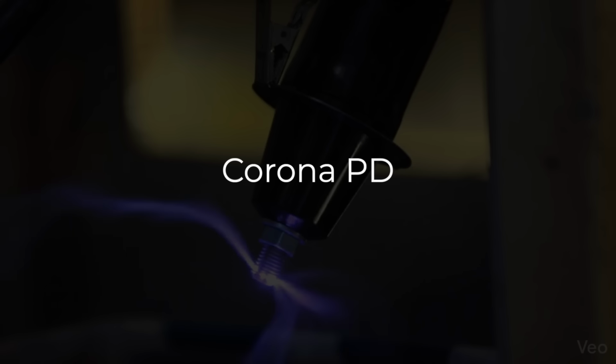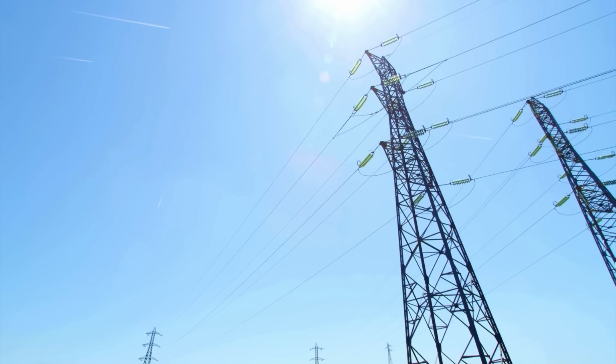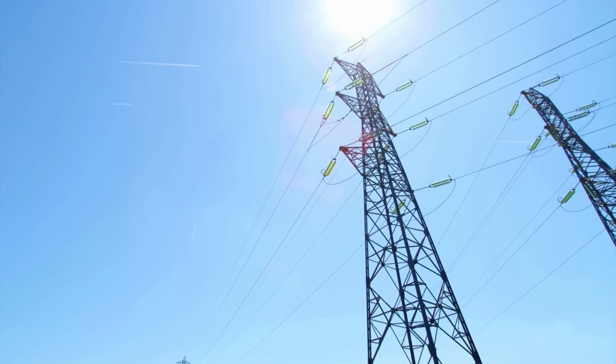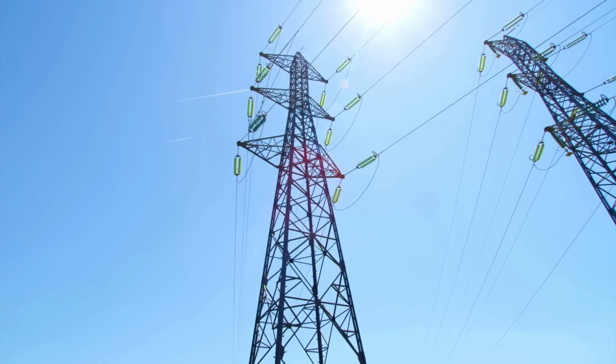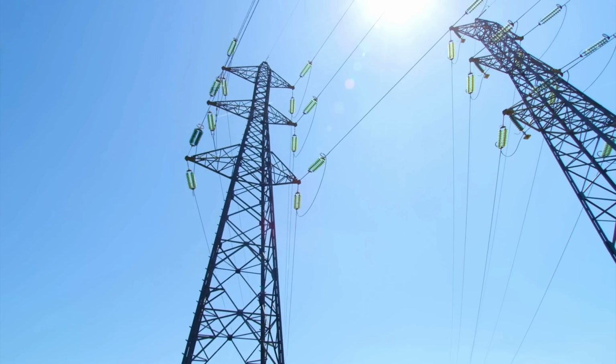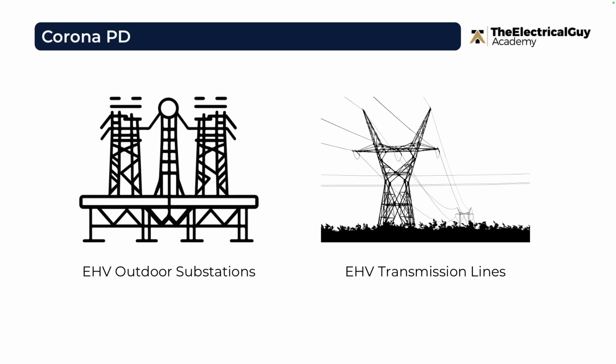Let us first start with the not so evil partial discharge, the Corona PD. If you ever walk near a 420 kV, 550 kV or 800 kV transmission line, you may hear some sort of hissing noise, or if you're traveling in the evening period, you will see even the violet glow. That basically is the Corona partial discharge. Now, this Corona PD is generally seen in the extra high voltage outdoor substations. Even the equipment that we use in that substation might face this particular issue. And also the extra high voltage transmission lines face the Corona problem.